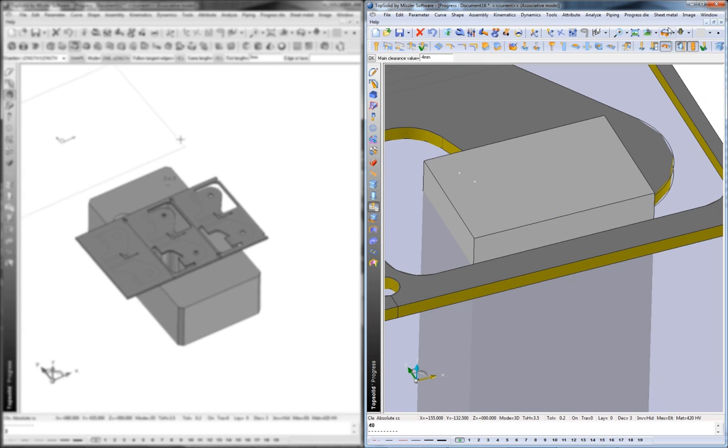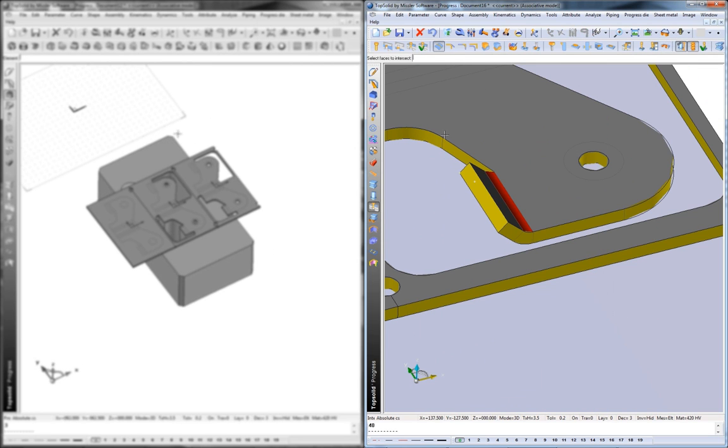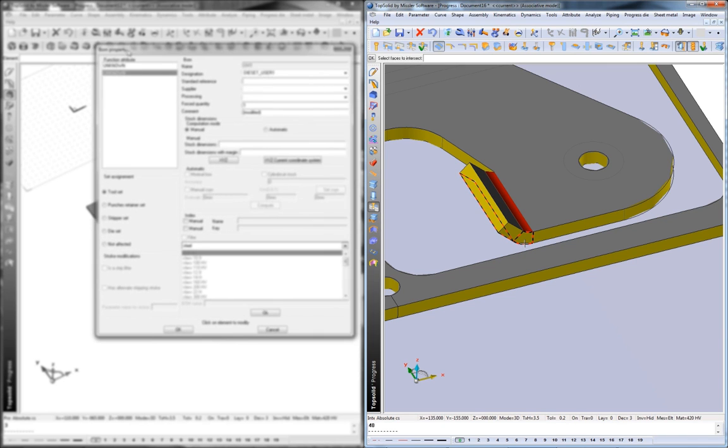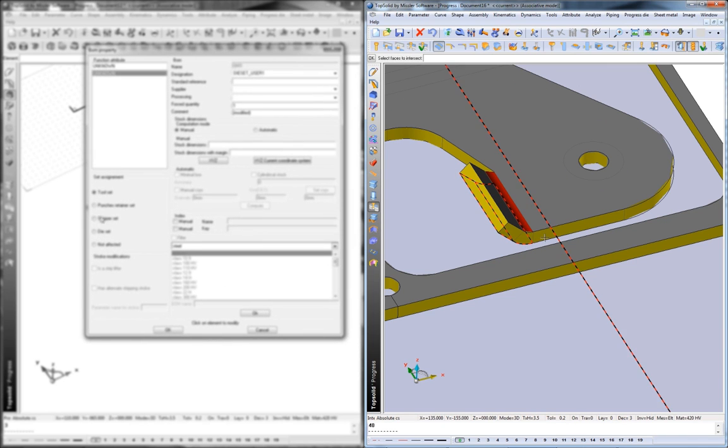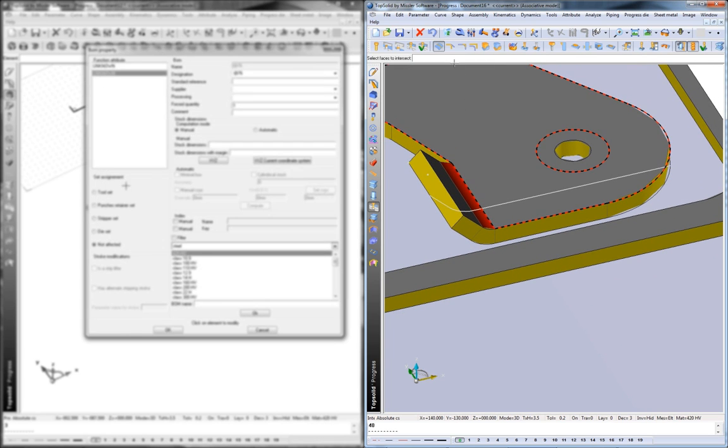User 2 has been quietly chugging away, and he's working on the bend shapes. Let's see what he's doing. Here he's asking TopSolid to help him create the profile needed to make his bend shape. There you can see the profile has been created, and now we're going to show our die block.